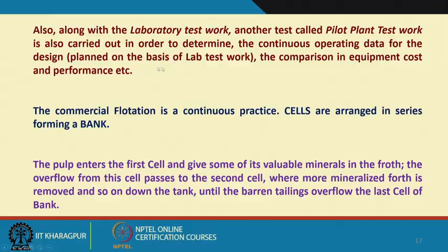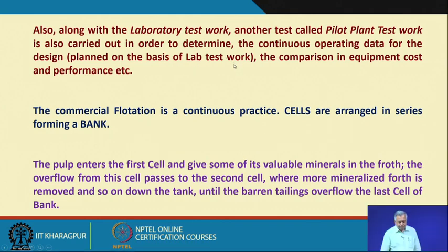For that, I have to have a pilot plant test work, with a comparison of equipment cost and performance, etc. You use different types of cells, maybe different types of peripheral equipment like your conditioning tank, what type of pumps I will require. Everything you just optimize in a pilot, based on pilot plant test data, along with the performance of your flotation process.